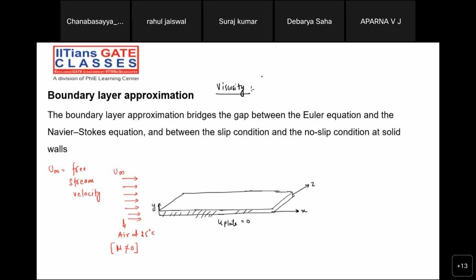It is a property of the fluid element in such a way that it offers some resistance to adjacent fluid motions, right? Suppose two layers are flowing in the same direction, but one layer is flowing with velocity u and the other fluid layer is moving with velocity u plus du. What will the communication be between the second fluid layer and the first? The second fluid layer will say come back, and they will apply a resistive force like this. Is it correct? Check it out.